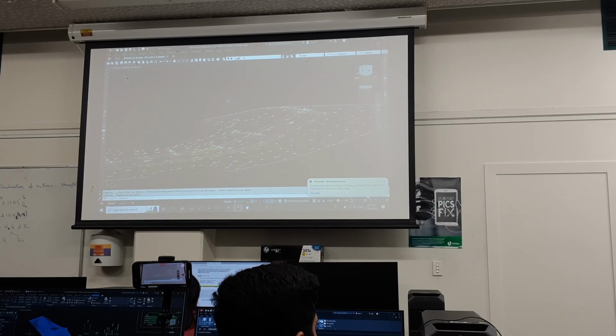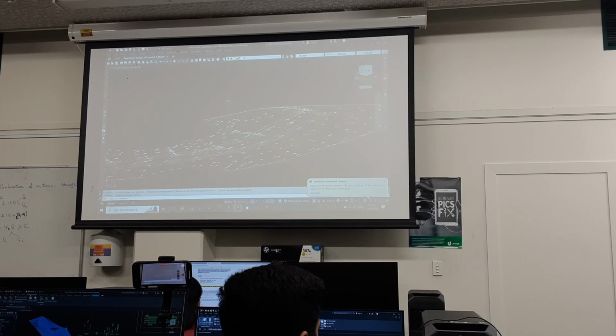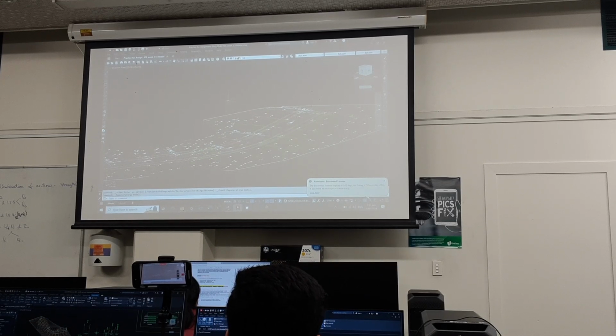You might like to just bring the centre line forward into CAD and then just put it in the right place. Or you might like to just bring the, when you get up to week 2, the surface, bring that through. Alright? I prefer the idea of turning them on and off and then bringing it through. Remember, if you've got a common point, you can always move something from a common point to another common point. So bring it through and lay it down over the top.